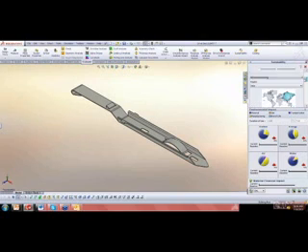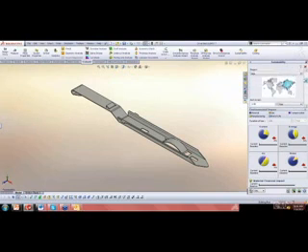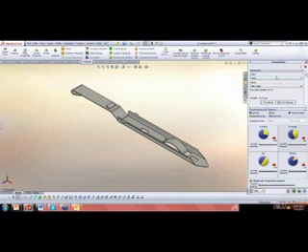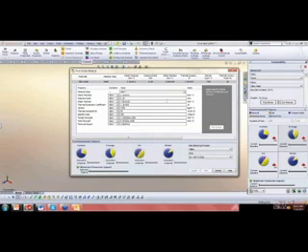Usually for users, what we can change more is the selection of materials and the process. So currently it is steel and alloy steel. We can use Find Similar. Here are all the mechanical properties: material class, elastic modulus, Poisson ratio, shear modulus, thermal expansion, density, and so on.